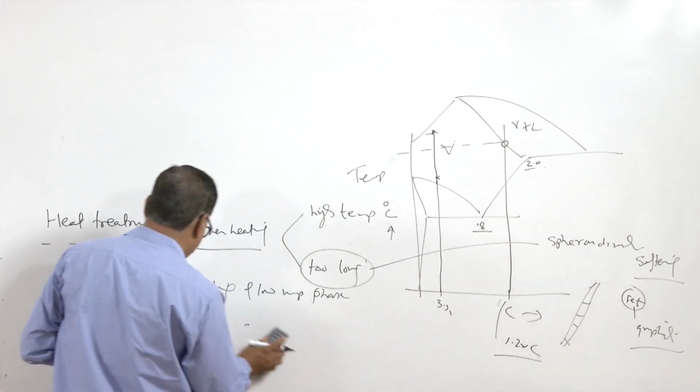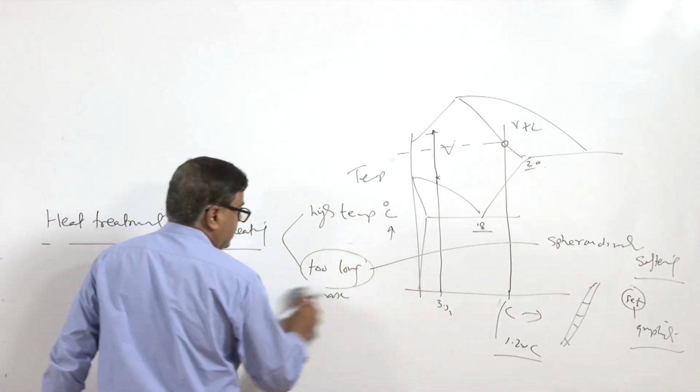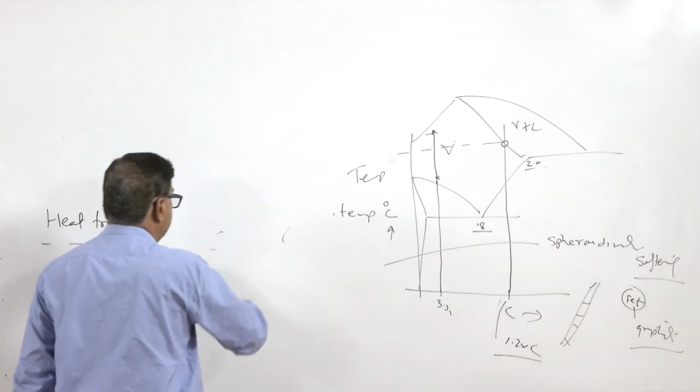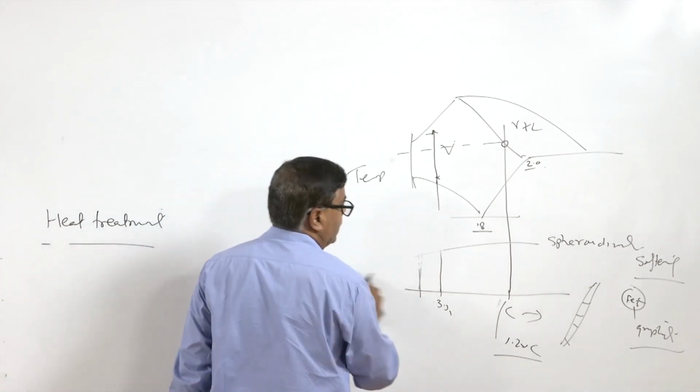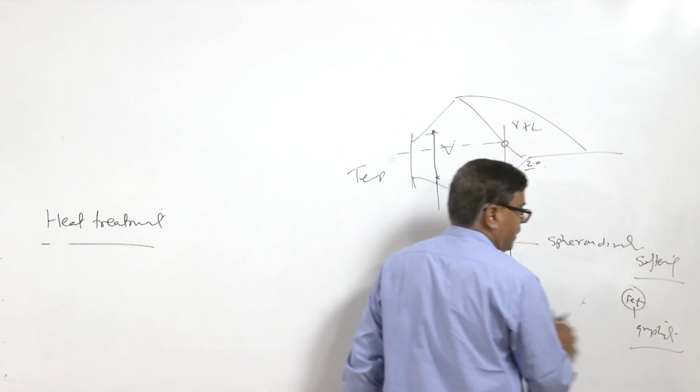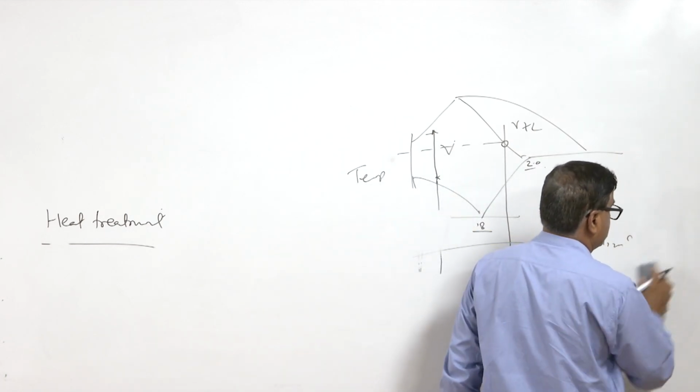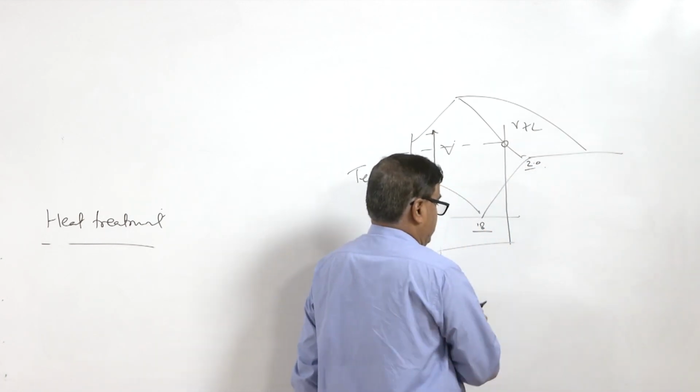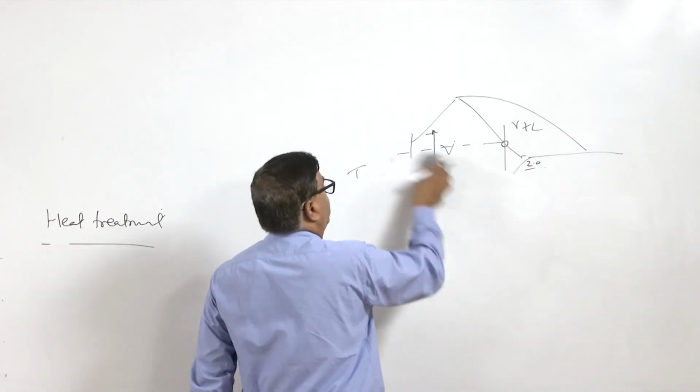effects can be there. As I have said, partial melting can reduce the ductility and the toughness, can increase the notch sensitivity, and can reduce the resistance to fatigue and the tensile load carrying capacity.